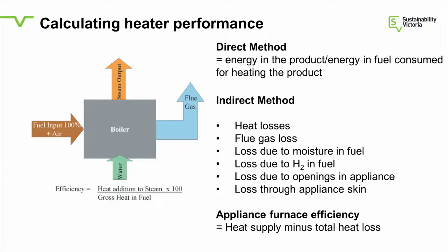The difference between furnaces and boilers is that most furnaces and ovens are a lot less efficient because of the higher temperatures or higher airflows than boilers. So there's normally a lot more potential in heat recovery for direct process uses than for boilers.